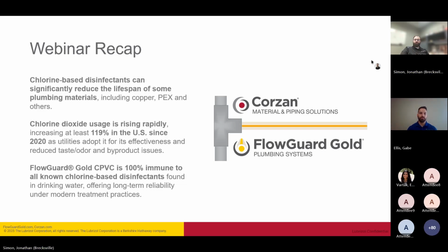It looks like we got a question from Marty, what's the quickest failure on new PEX after installation in a home due to chlorine dioxide? So we have seen with just free chlorine failures in about 7 years. But with chlorine dioxide, we've seen examples of failure in anywhere between 2 and 3 years after installed in a new home.